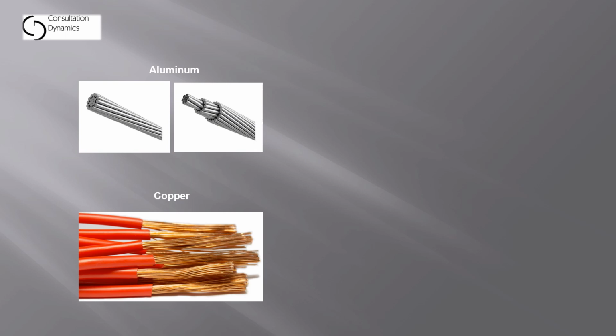And even though aluminum is less efficient as a conductor because of its high resistance, if we step up the voltage and step down the current, relatively speaking, the losses aren't so great and aluminum becomes an ideal product for high power transmission. Copper is certainly more efficient, but because of its weight, you need to have 3 times the number of towers, and it would be 3 times as expensive for the basic wiring, and so that wouldn't make sense to use copper in high power lines.